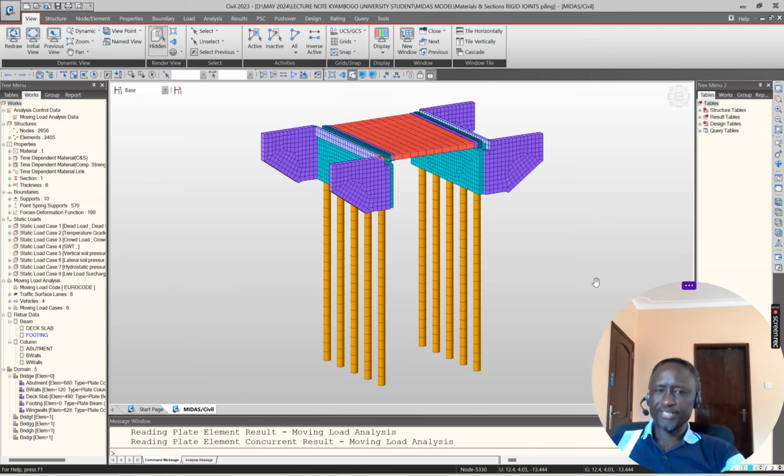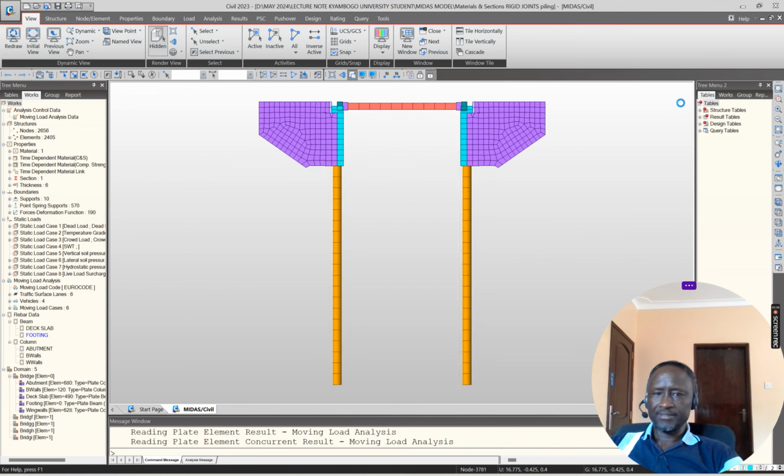This time I'm just demonstrating to you the same bridge, foundation truncated, and we have introduced the pile foundation, assuming that the soil demands use of pile as investigated by the geotechnical team. This pile, I assume the length about 20 meters, diameter about 0.8 meters, and then connected onto the vertical abutment.